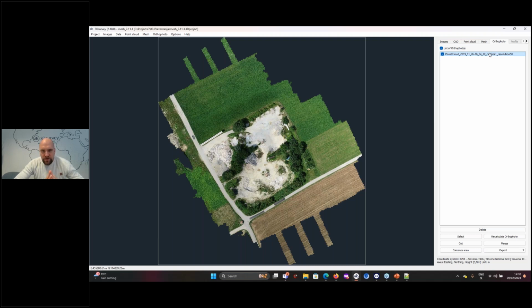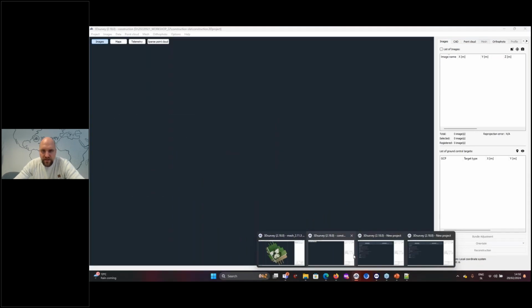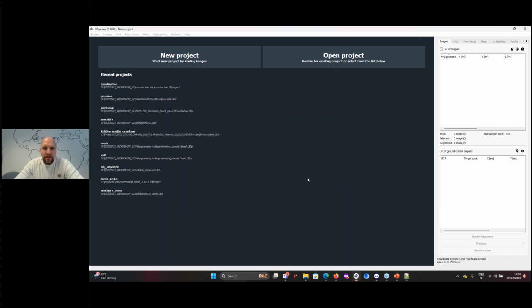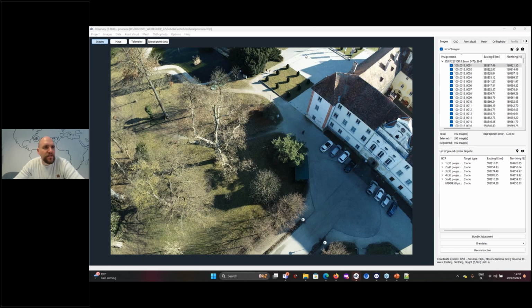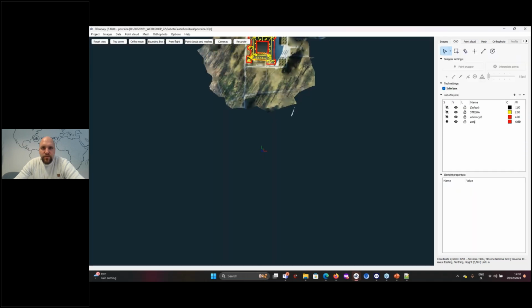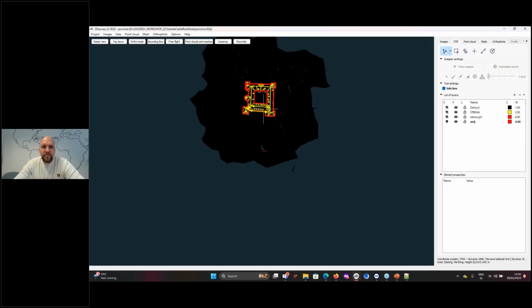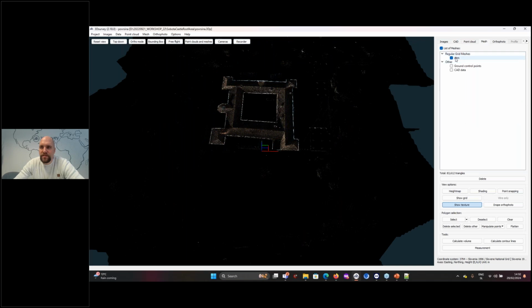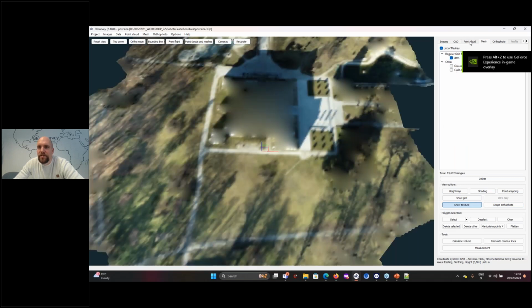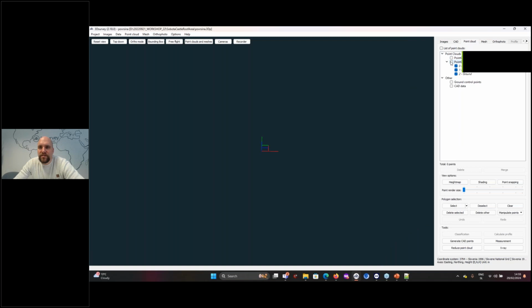Now I want to go into a little bit more detail, and I have already opened a second project here. Let's wait for it to load. In this second project, I will show in more detail how CAD functionality works in 3Dsurvey. Here I have some data already set up. I'll right-click here, remove texture. Right, the point cloud is currently not visible. We will turn it on.